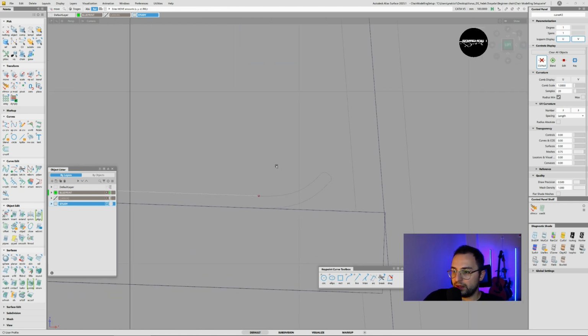Okay, we need some sort of arc here, so let's create one more curve by holding down left click. Right now, if we add one more CV row, instead of playing like this, we can of course position it, but the right way is come in here.